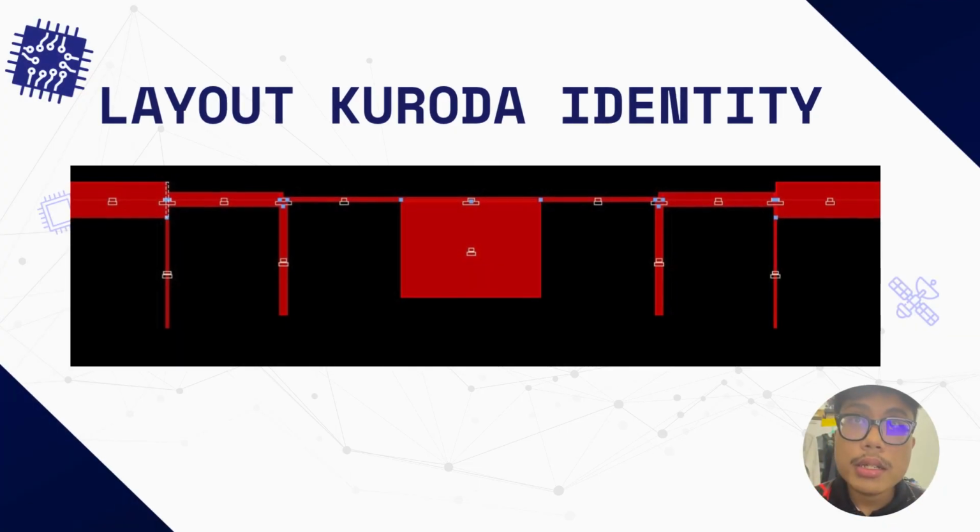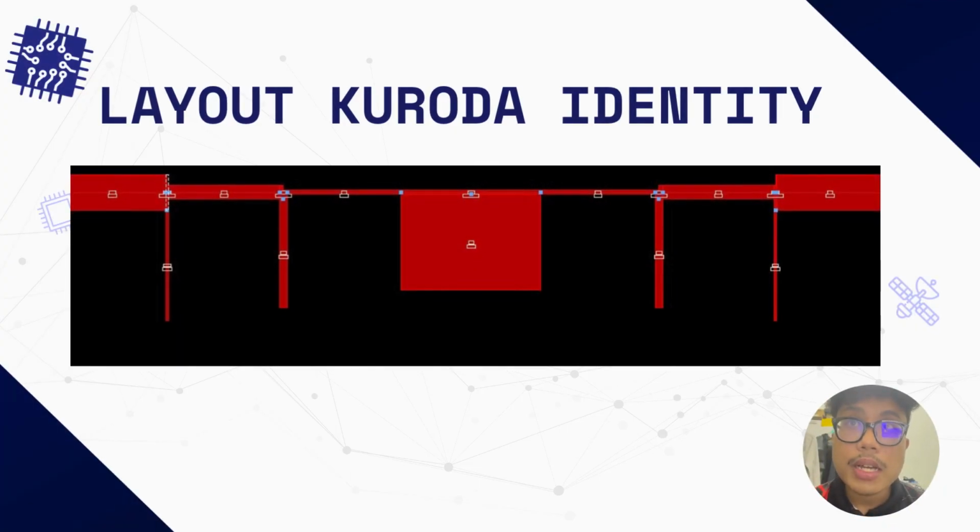Okay, next is the layout of the Kuroda identity. Here is the physical layout of our discrete filter. This is the microstrip realized using transmission line and open stub. The layout shows the actual geometric dimensions calculated based on our substrate parameters, the dielectric constant of 4.4, substrate height of 1.6 mm, and conductor thickness of 5 micrometers. The layout demonstrates how the theoretical circuit translates to a practical fabricable design.